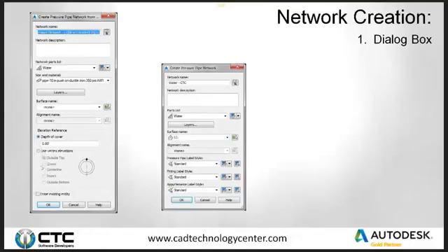But the other option in here is actually to use vertex elevation. And with this situation, I can specify the top of pipe, which is kind of defaulted right now if it was selected. I could pick the crown of the inner diameter, so it would pick the highest point of the ID.